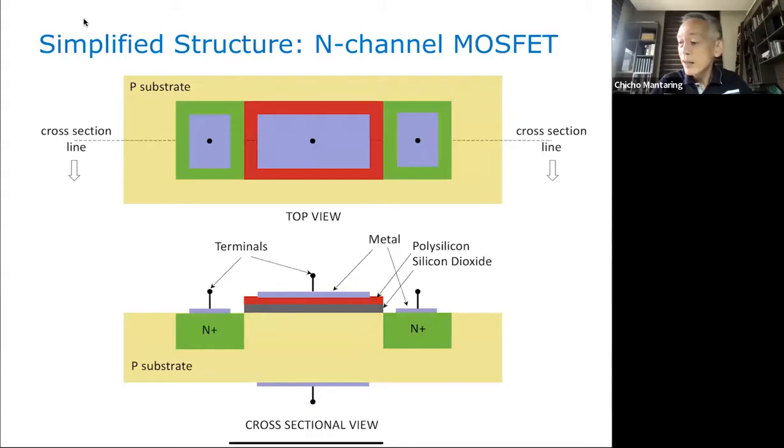The characteristic of polysilicon is it acts like a simple conductor. And then you have metal that is deposited. This is metal, you also have metal here, and you have metal here. And on that metal, you have your contacts. So these are now your contacts or your terminals. Okay, so this is the cross-sectional view of your N-channel MOS transistor.